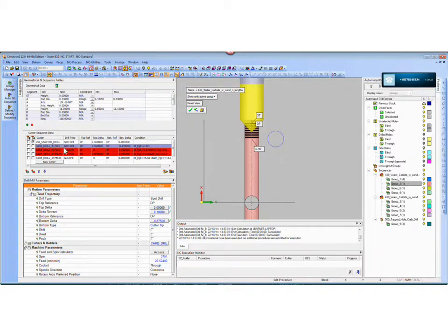drill. And then each one of these has a range. So this tool with a, well, this one's also a 5 length ratio, and the reason is because it may be possible that I can finish the hole with that drill. So if that's the case, I want to go ahead and finish the hole. That's what this line says. And then this one, of course, is the 15 length ratio, and here's the 30 length ratio. So I set up these conditions. I define a range this tool would be appropriate for, and then it just processes. It looks at the ranges, matches it to the conditions, and it programs the holes automatically. And it really works nice.